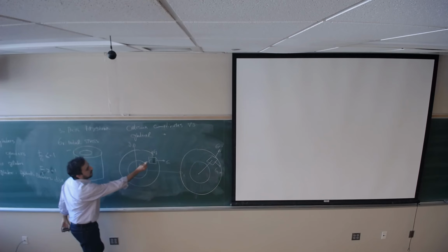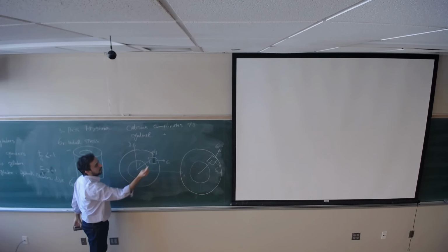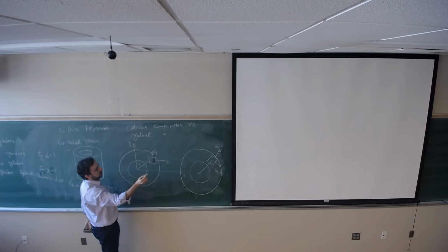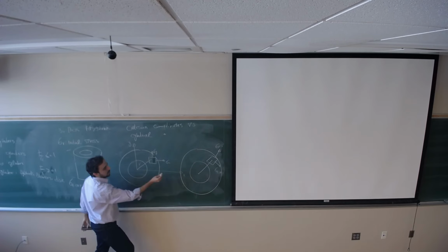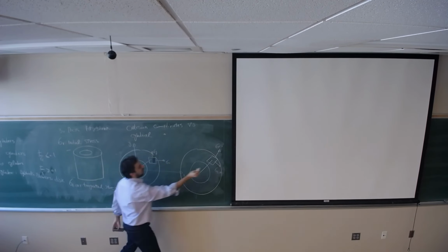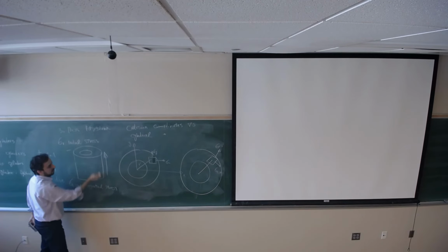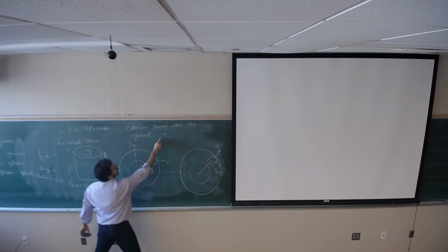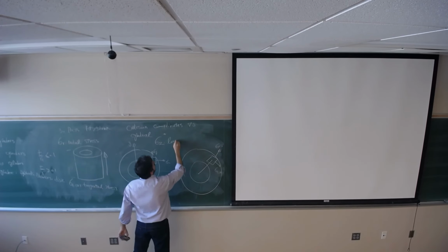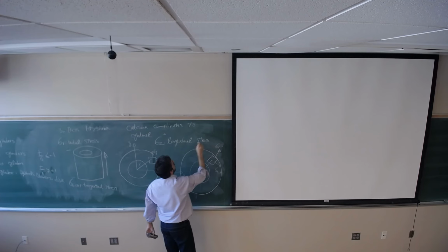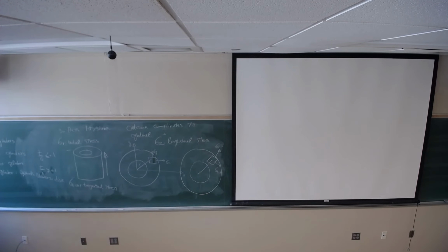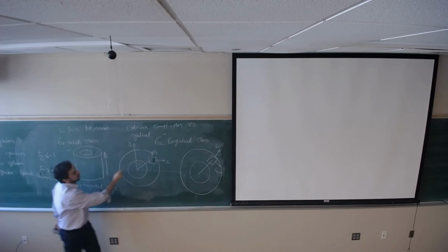Here, the stress applied in this direction is called sigma z. If we have planar stress, it's going to be 0, but if it shows up, we are going to have sigma z. Here also, we are going to have sigma z, which is applied along the cylinder. We call it longitudinal stress. So radial, tangential, and longitudinal stress, which applies along the cylinder.